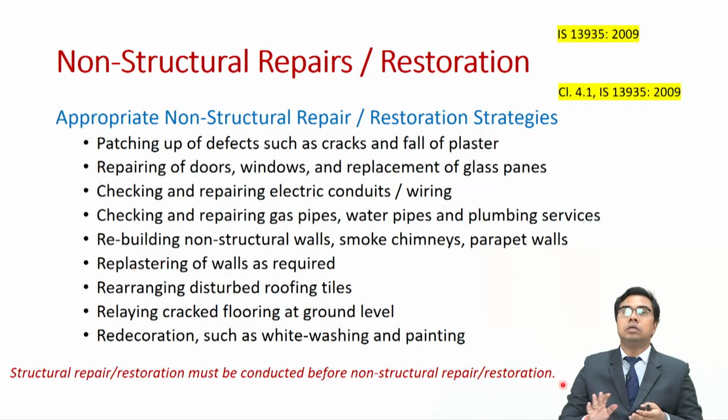Why? Because suppose your slab is having a damage and you only rearrange the disturbed roofing tiles. From outside it will look perfectly fine, which will give you a false impression of seismic safety, but it is having a real problem. So that is why you must implement a structural repair or restoration prior to non-structural repair or restoration.